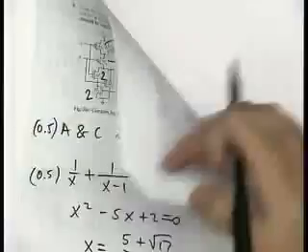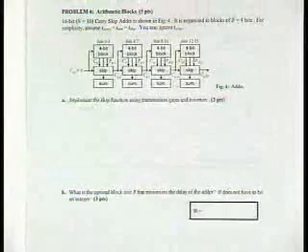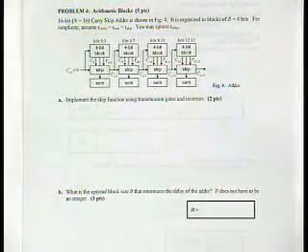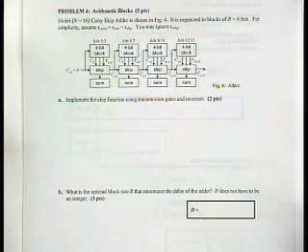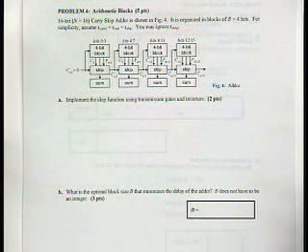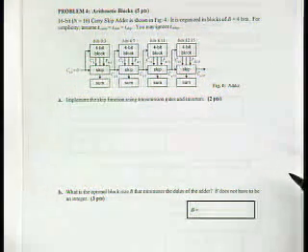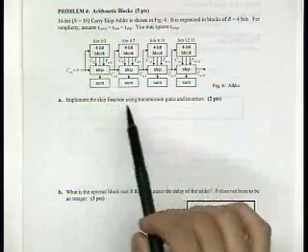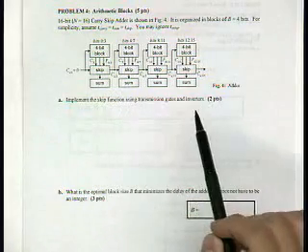And then finally, the question about arithmetic blocks. This was a carry skip adder. I think a lot of you were ready to tackle carry look-ahead too, but that was late in the lecture, so we didn't want to do that. Looking at this block form, you have to recognize the functionality of this adder and implement the skip function using transmission gates and inverters.